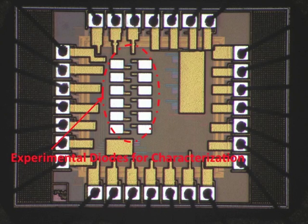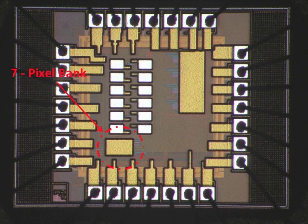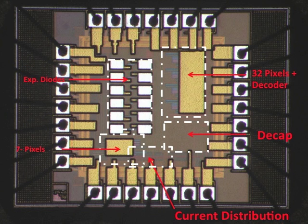Our IC design was divided into 5 parts: experimental diodes for characterization, 32 switchable pixels, diodes, and decoder, 7 pixel bank, diodeless test pixel, current distribution network, and decoupling capacitor.